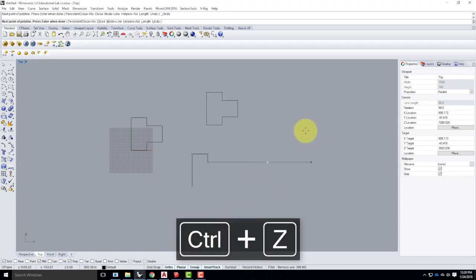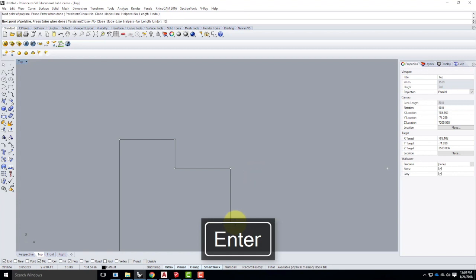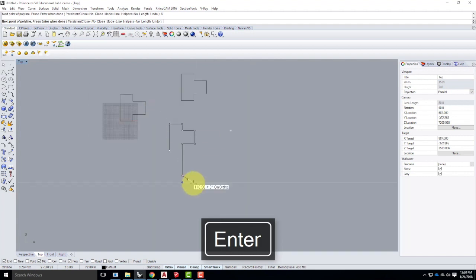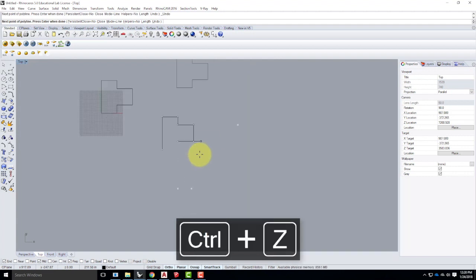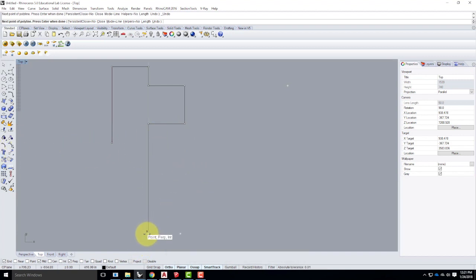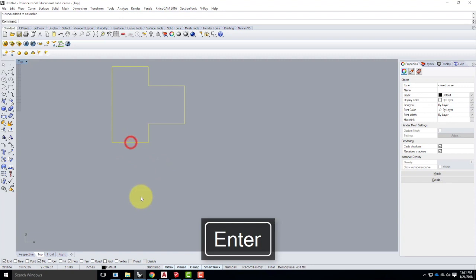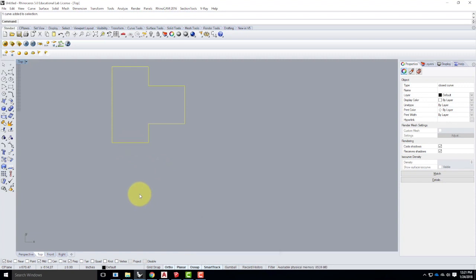So that's another option. Sorry, I had some control points. So let me continue on. 12 feet in that direction, 12 feet in that direction, 6 feet. Oops. Sorry. I have some snap points that are set. We'll talk about those in just a second, but it's making my life difficult right now. There we go. And then I can type C for close, and I get this shape, which is the shape I've been drawing over and over again.